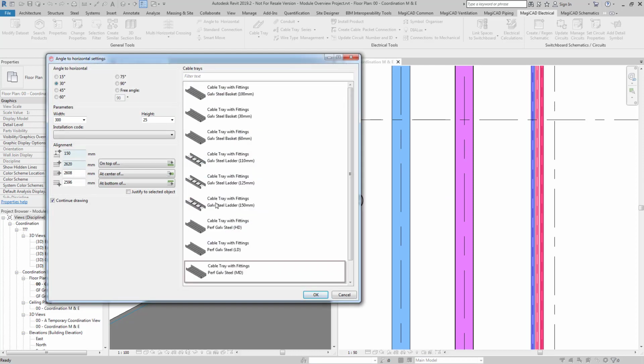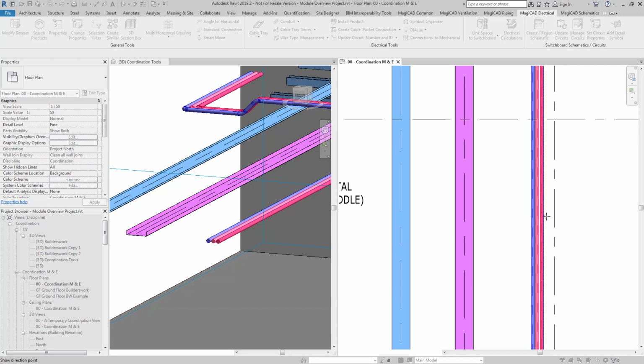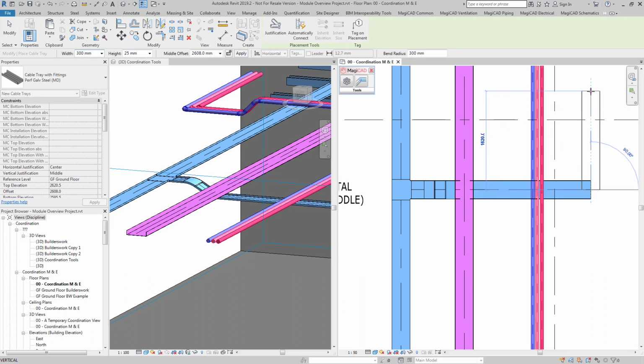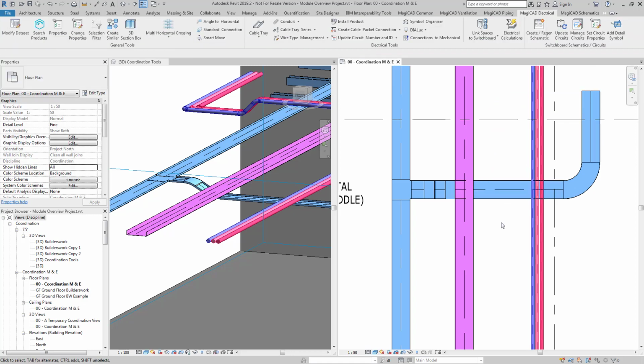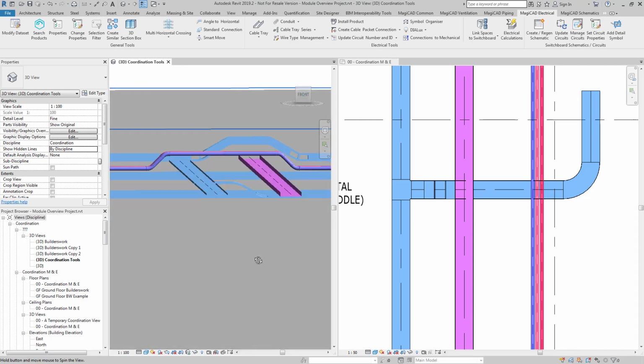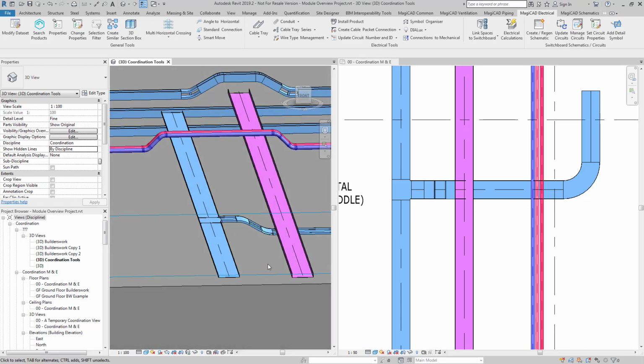and using the settings in this configuration tool, we can create the adjustment automatically, and then from there you can continue drawing as normal. What this will then achieve is it will allow you to create this set down, in this case off the side of your cable tray, with 150mm tolerance underneath the adjacent cable tray.